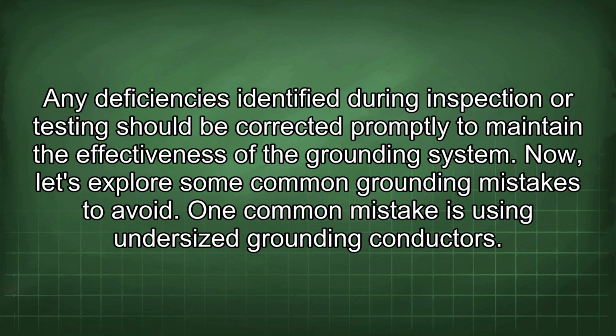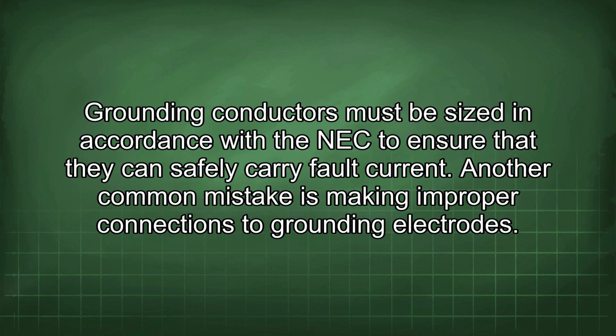Now let's explore some common grounding mistakes to avoid. One common mistake is using undersized grounding conductors. Grounding conductors must be sized in accordance with the NEC to ensure that they can safely carry fault current.